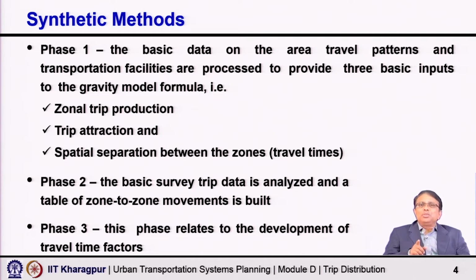So, if I want to translate it to Fij, then that Fij curve or function needs to be calibrated. To calibrate that Fij, we also need to know how much zone to zone movement is happening today. That means, given today's production, today's attractions and today's travel times, if travel time is used, then how much travel is there, or what are the Tij values?